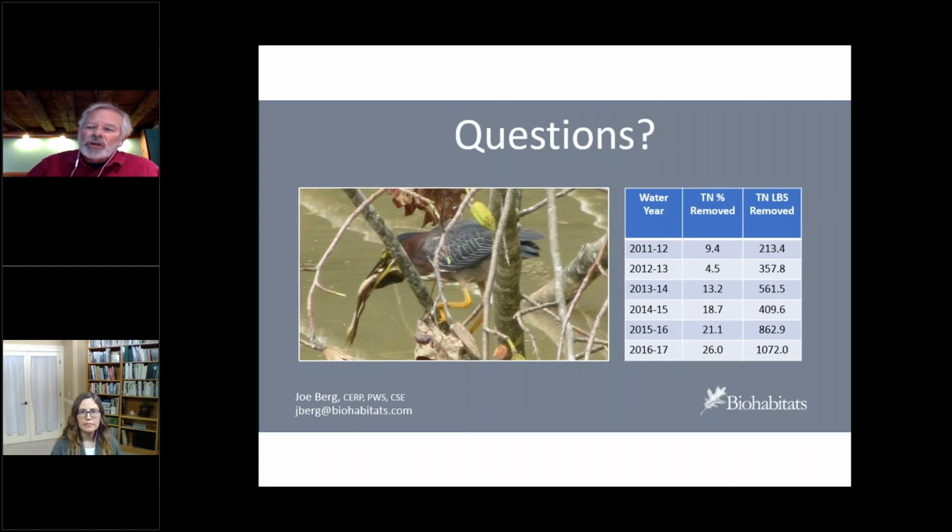I think you could make an argument for looking at your drainage area and your surface treatment area, and people in the past have done that with wetlands, but I think you end up seeing just how variable these systems are because of other factors, like the watershed draining to it and its characteristics, the temperature regime, the time of year that you're trying to do the treatment, because you can definitely expect different performance in the summer versus the winter with these kind of passive wetland treatment systems.